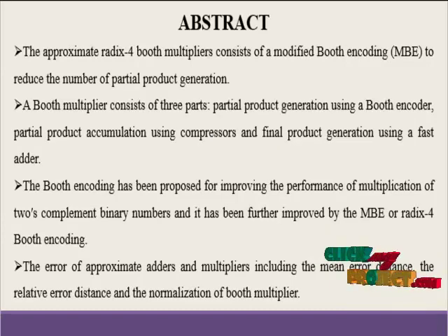The approximate Booth multipliers are designed based on the Xilinx VHDL language. The approximate Radix-4 Booth encoding in the current design of the multiplier can use the truncation model of the simple approximation model. The low part of the partial product, the least significant partial product, is estimated by a constant value for the multiplier's input.